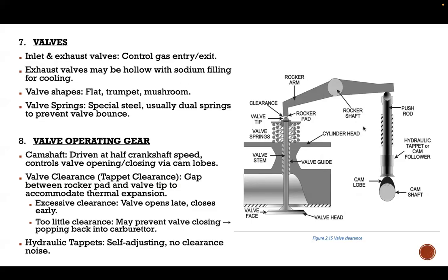So this is the job of your valves, that is to open, and when you open them you're going to have fuel or exhaust air going in or out, and when you close them nothing is going to flow. That is going to be your other two strokes. In engineering we used to study how to design this, by what degree you have to open it and by what degree you have to close it. When we talked about your practical Otto cycle, we said we are going to lead the opening of your intake valve and lag the closing of your exhaust valve and all those things. We have to design all of that using your camshaft, because with your crankshaft we can't do much about it, but with your camshaft we can alter the shape of it, so it can open and close either early or later.